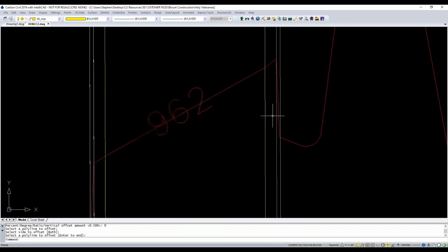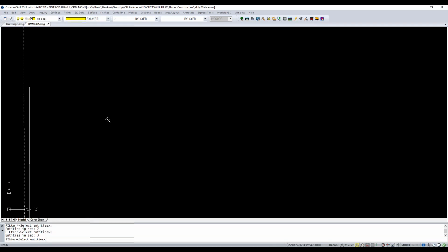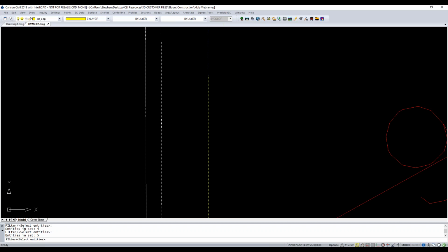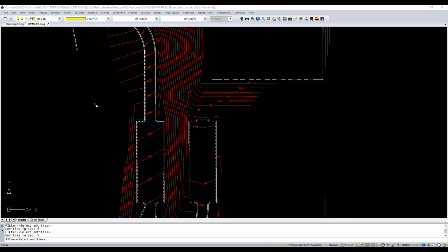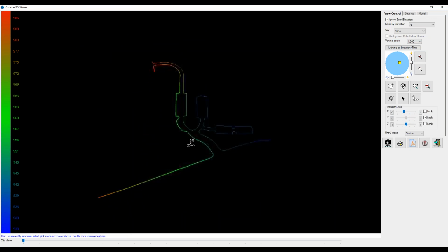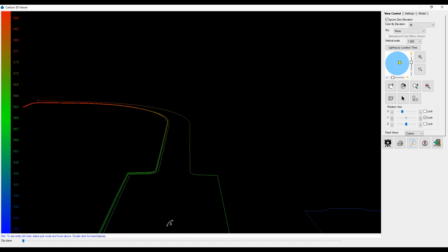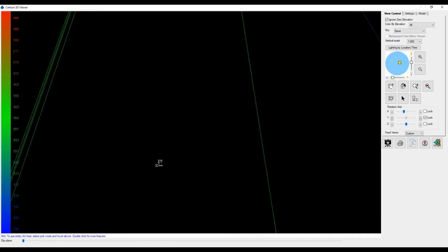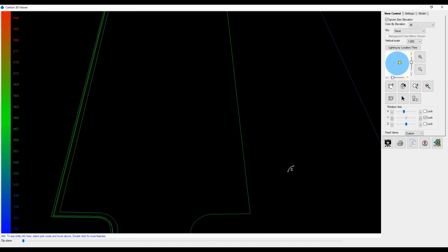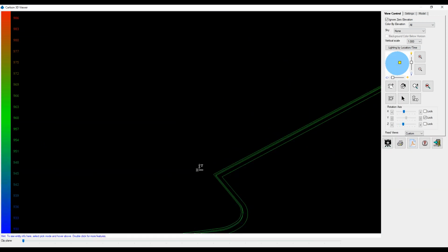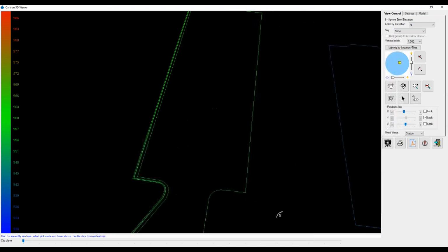All right, so let's see what we have. It's not going to show it over here because I'm not going to repeat it on that side, but we'll do a 3D view, drawing viewer. We'll select our EPs and our offset lines. Hopefully I'm not grabbing the 2D lines. I should have turned them off, but hit enter. And now we can see everything is elevated. So we got some decent data here. Also, this is a good way to check and see if you see any spikes or dips where it didn't model correctly.